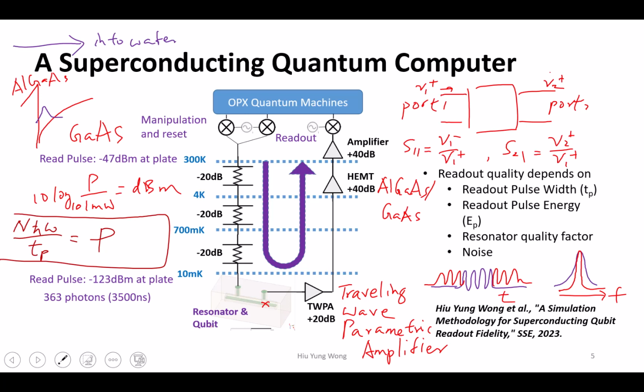My understanding is this is a non-demolition readout. Let's say we discuss spin qubits, which deal with electrons. Usually when you're doing Pauli spin blockade experiments, it involves tunneling an electron from one place to another, usually a reservoir, so that electron is lost. As a result of the readout, you can still do the measurement, but now that electron is lost, so that's called a demolition kind of readout method. Whereas I think usually reflectometry does not involve that kind of operation.